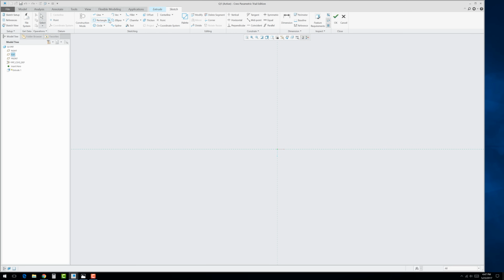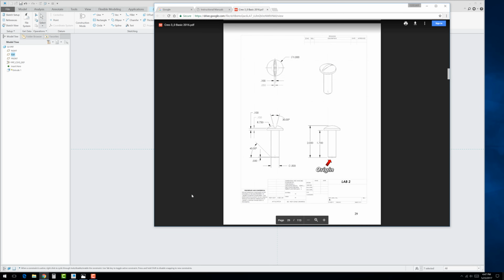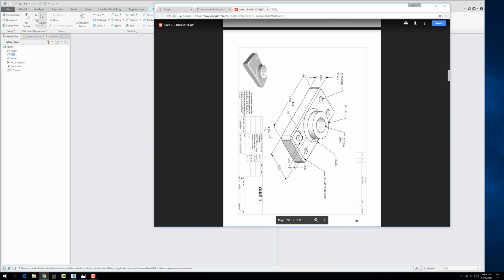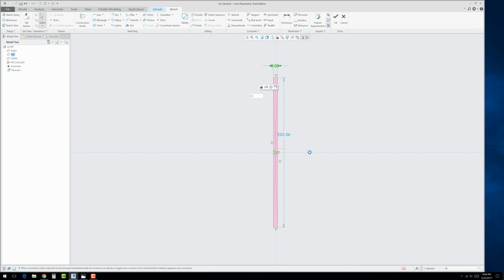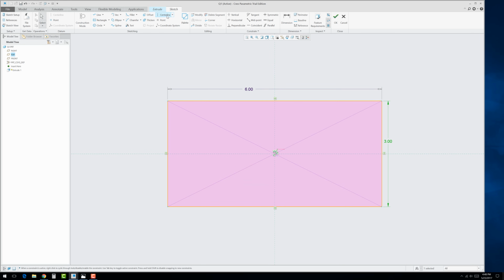And now go to the center rectangle tool, which I showed you last week. Use the center, go up to the center here, drag this out, and let's set the parameters for the quiz. It's kind of hard to read here. 6 by 3, so 6 wide by 3 inches. Oops. There we go. Now draw a vertical and a horizontal center line for mirroring purposes.